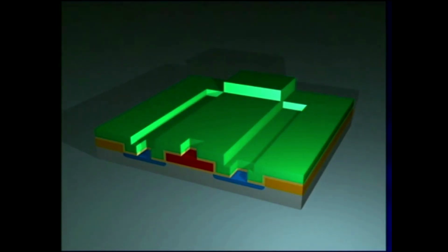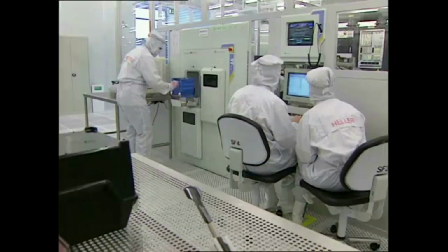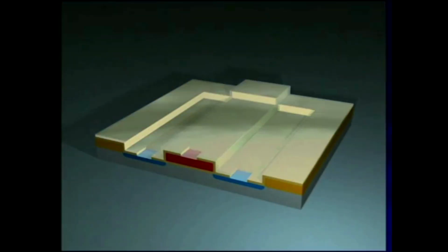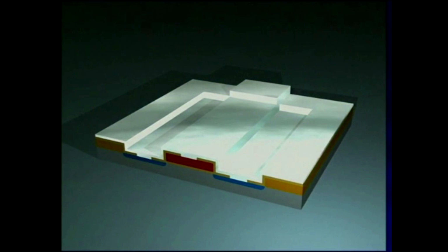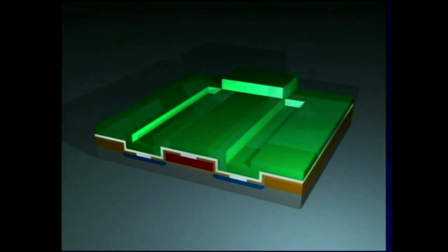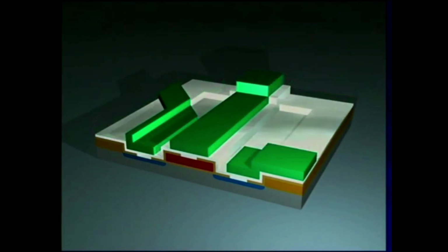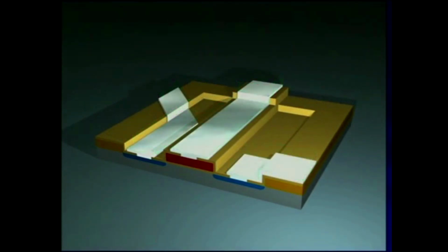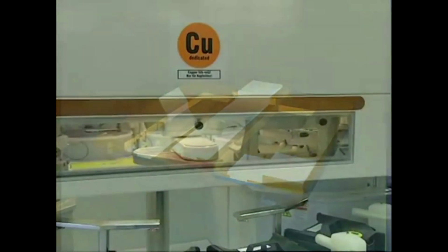Contact holes are etched in to open up access to the conductive layers, because the contact and interconnections must now be deposited. For this purpose, metal compounds are sputtered onto the wafer in sputtering machines. Once again, photoresist and mask; depending on the component, over 200 meters of interconnections are created. The unexposed strips show the path of the aluminum conductor tracks that remain behind after the etching process and provide the contact to the underlying layers.